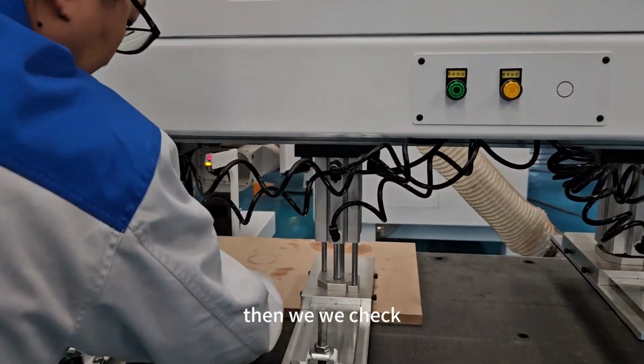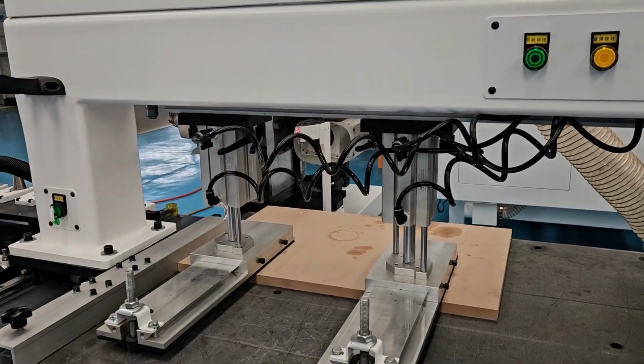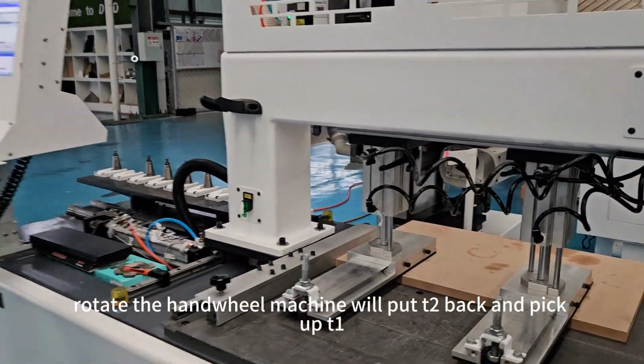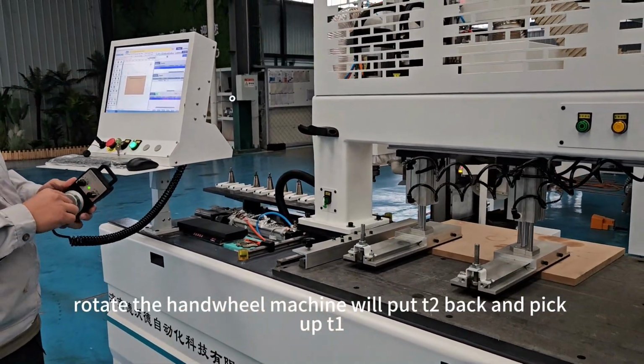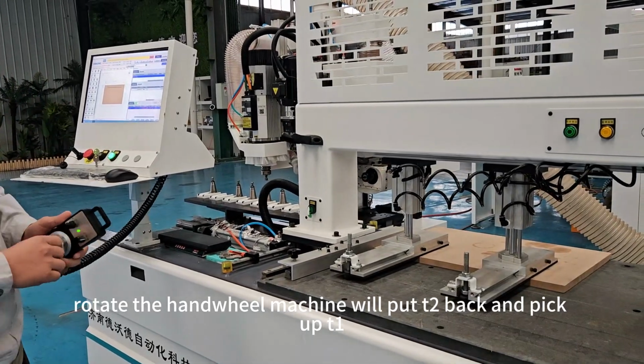Then we check. Then we start to rotate the hand wheel. Machine will put T2 back and pick up T1.